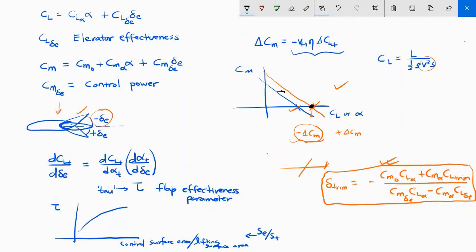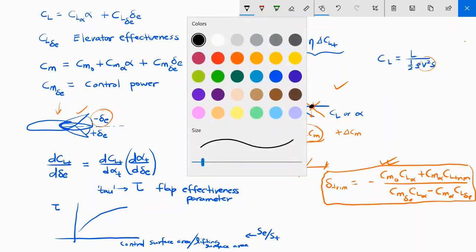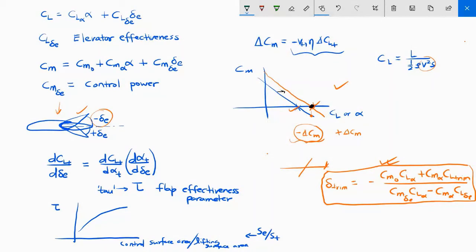Now forget the physical components. If you just think of this mathematically, we can then try to imagine how such mathematical conditions can be fulfilled physically. So we can try to build a solution with this sort of thinking also. How about if I want to trim the aircraft at a higher value of CL? In other words, if I want to fly the aircraft at the same altitude at lower cruise speed, instead of shifting the curve, maybe I could have changed the curve and made it like this, right? I could have changed the slope of the curve instead of shifting the curve.